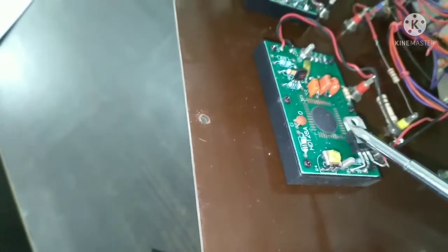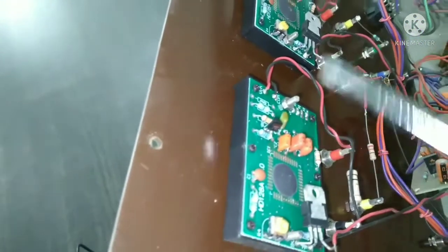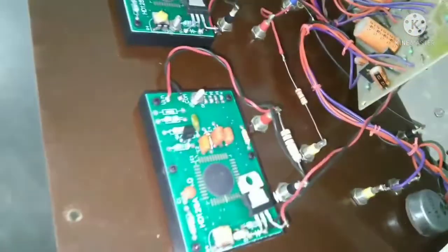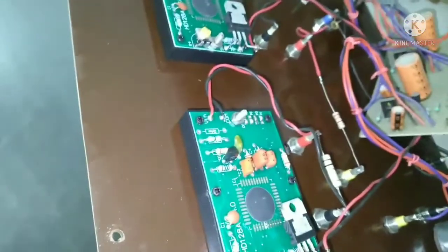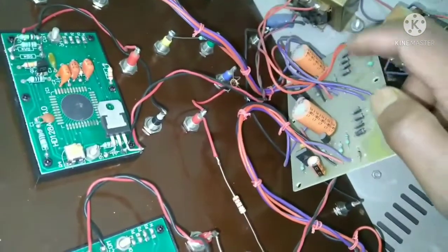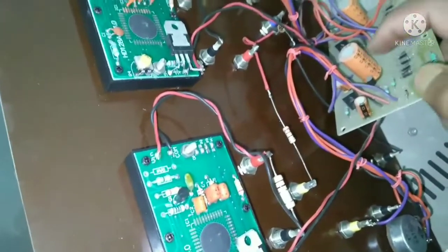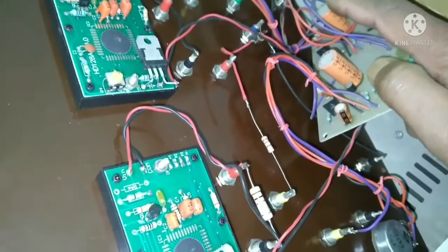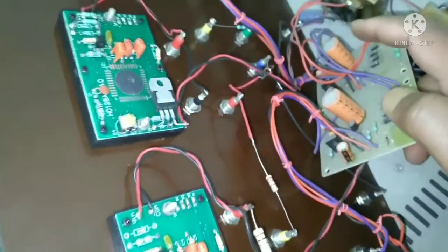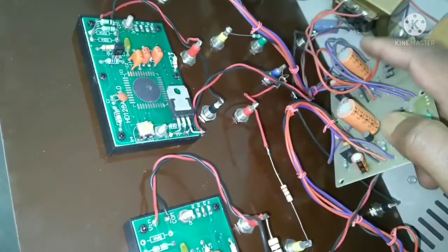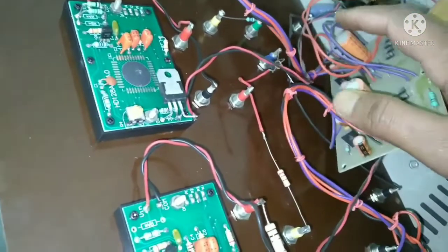Okay, these two regulators provide constant voltage for these two digital meters. And then you can see here from these two transformers, supply comes to these two bridge rectifiers. After these two bridge rectifiers, the output goes to capacitors. Okay, so these capacitors filter the pulsating DC, and then after filtering, it goes to, now here